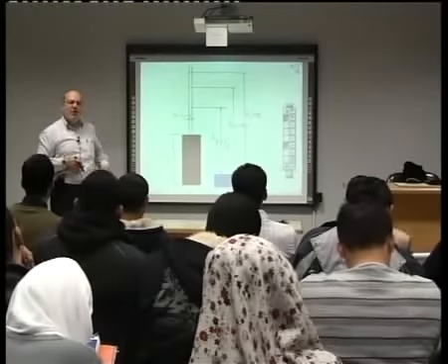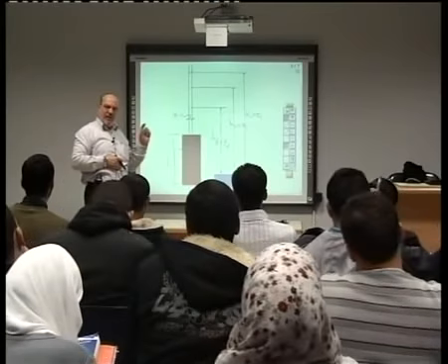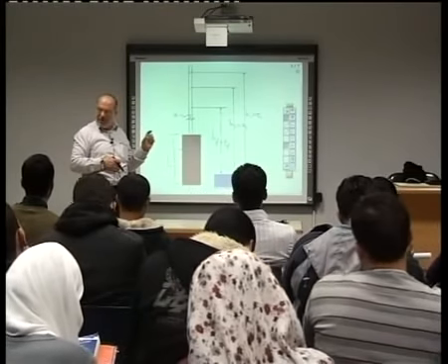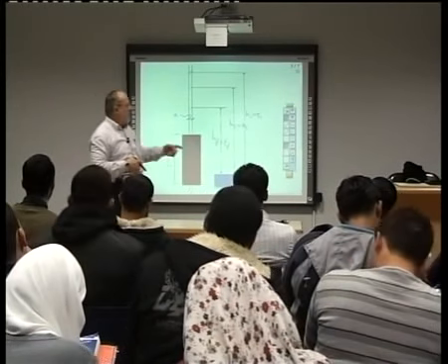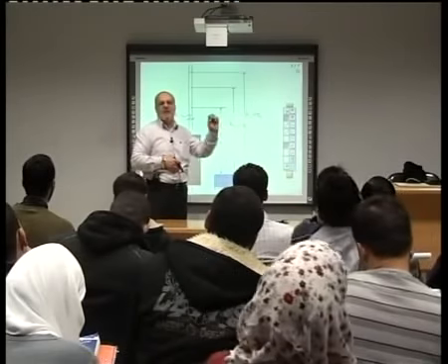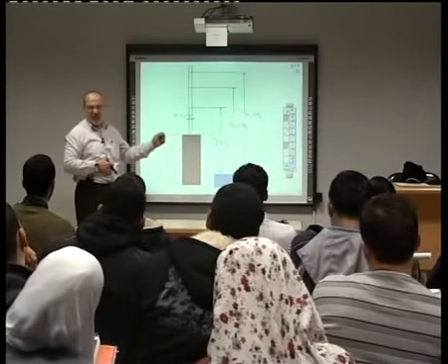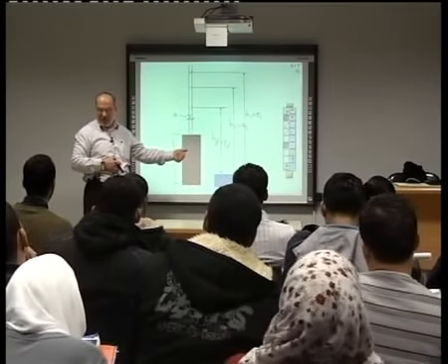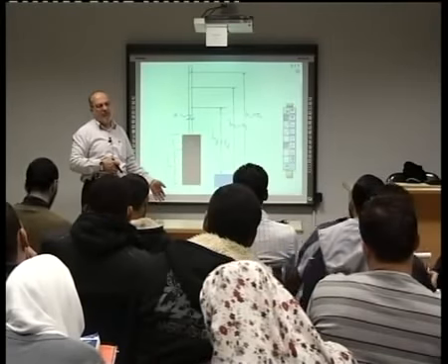So I can represent the permeability by the change of height versus the change of time, right? And to make it easier for you, I suggest have the first height, because it's fixed, at time 0. And then when I finish and stop the test, I will have the last height, easy to record, with the time for the test, okay?